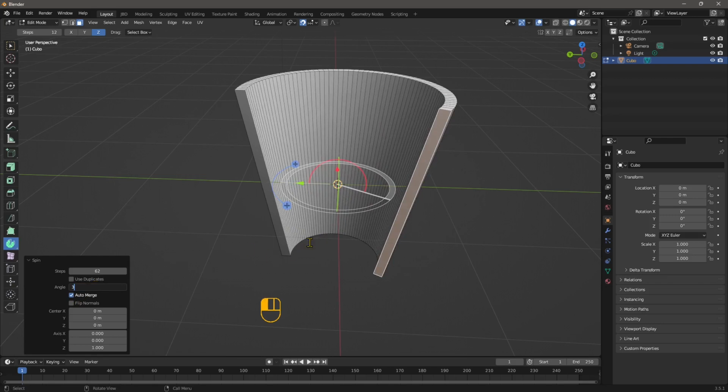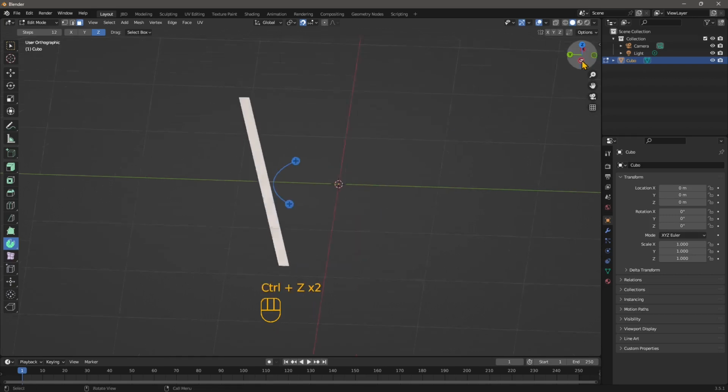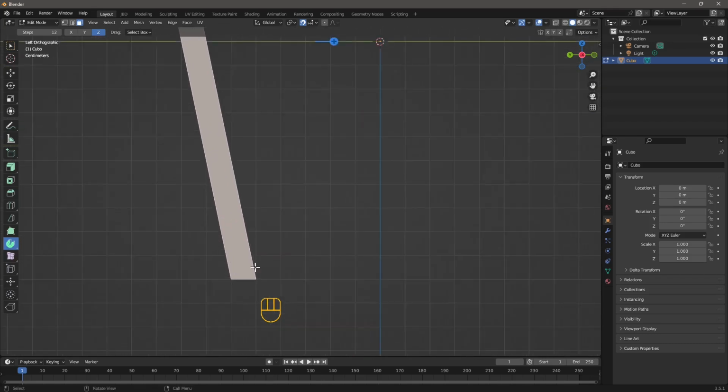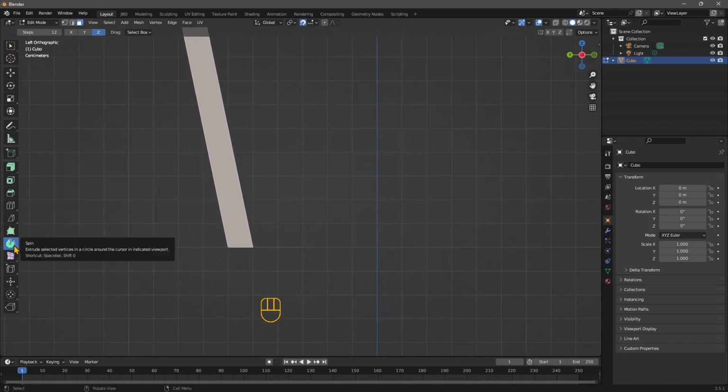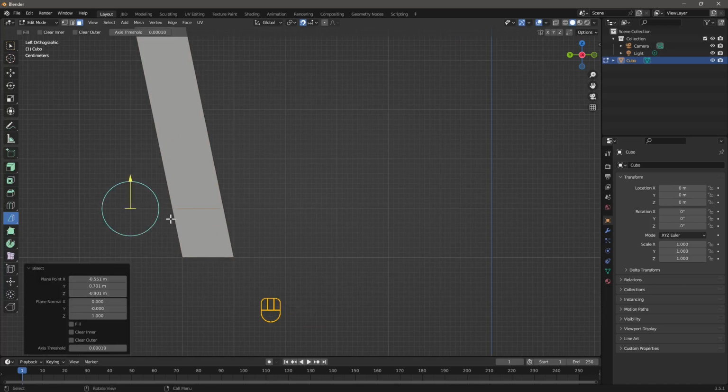But let's say that I want to create a glass and I need also a base down there. So let's go back to the shape. So let me just do Control Z, and let's make things a little bit more difficult. So what I'm gonna do is just create a cut where I can then define a base, and I will use the grid again. So I'm gonna select the face first, make sure the face is selected, and I'm gonna use the bisect, which is one of the cutting tools in Blender, and I want to snap it to this. So I want to click there and then hold Control so that it goes straight horizontally, and that's it. That's my cut.